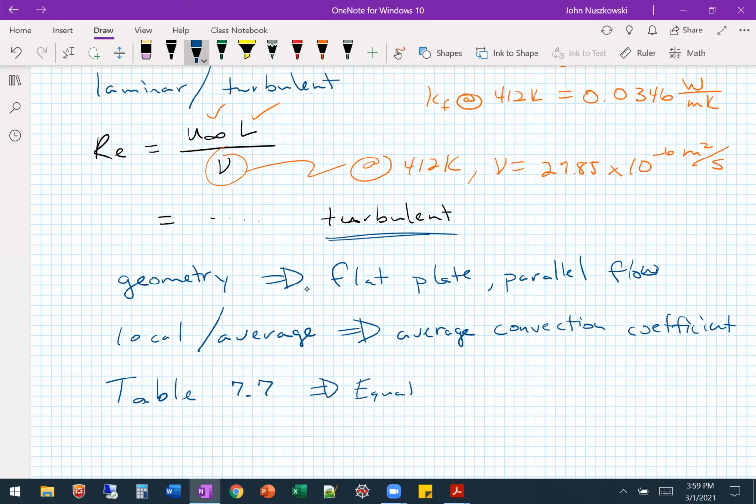So it has all the relationships, okay, for boundary layer thickness, friction coefficient, local Nusselt number, average Nusselt number for different geometries, laminar, turbulent, even geometries we didn't get to in the last section, like an impinging jet, a packed bed of spheres, a falling droplet, so different ones there too.